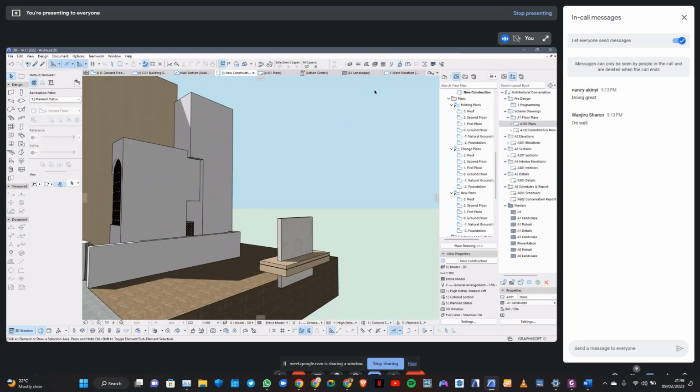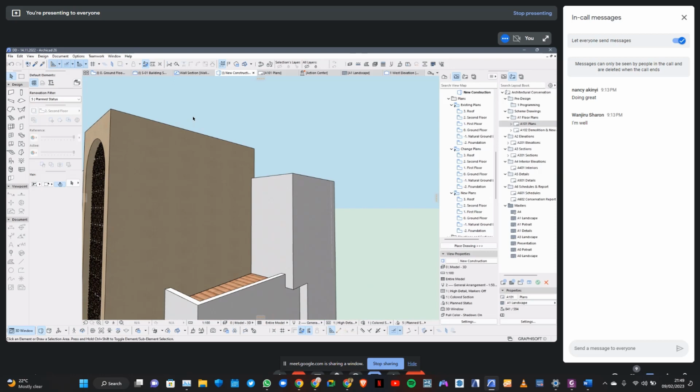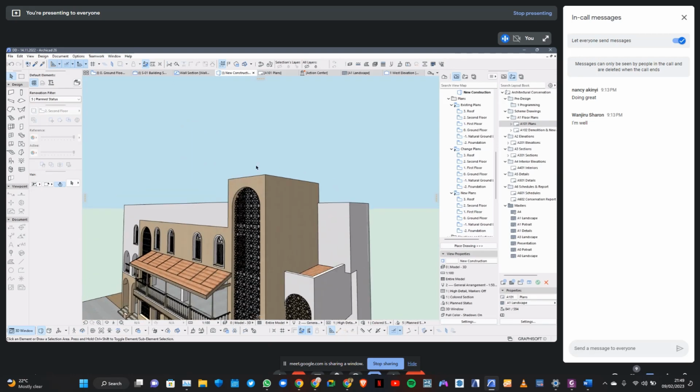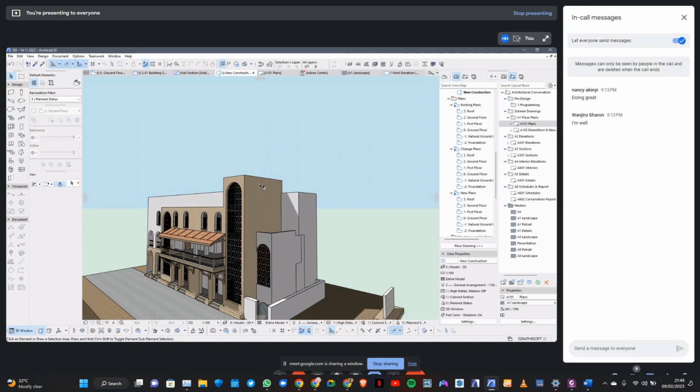Editing surfaces is a global setting, in that when I edit a surface, all elements that are using that surface will show that change. Or if I edit a building material, all elements using that building material will change. But now these overrides are what we call instance changes. They occur one at a time.